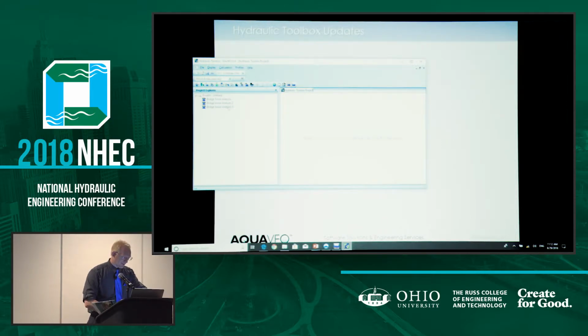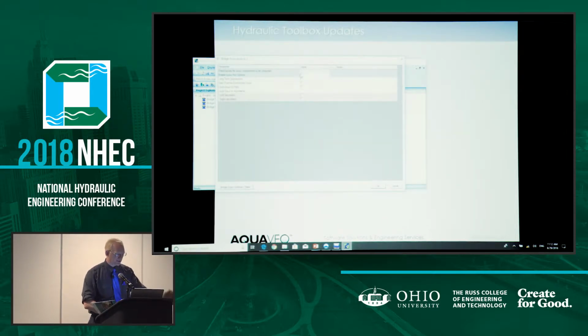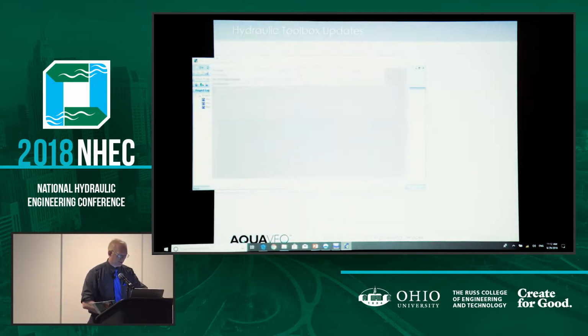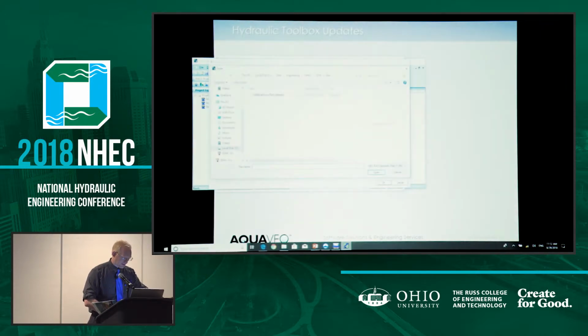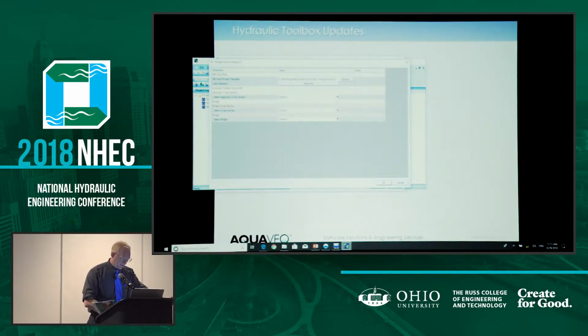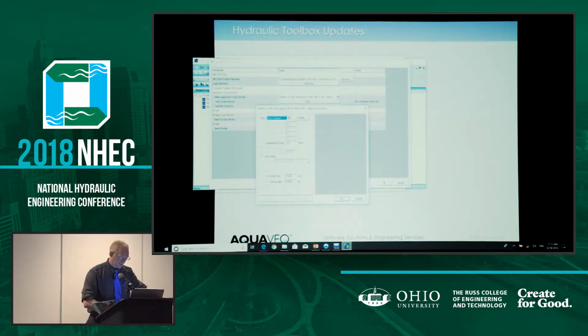To show you what we can do with the plotting, I'm going to enable the scour plot options this time, and we're going to import geometry from a HEC-RAS file. So this is just going to be coming into here, pull in our PRJ file. We're going to select our approach cross-section. I can click here to view it, which will bring it up in the cross-section as a channel in Hydraulic Toolbox. But I can plot it and view it and see what information is coming in. This is a viewing, not an editing at this point.